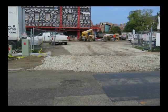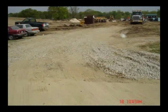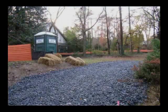Rock construction exits provide an area that allows soil from vehicles and equipment to fall off tires prior to being tracked onto the primary road. Thus, to be effective, egress from the site must be limited to the exit road. Exit roads need to be maintained periodically. This can be done by adding new layers of stone as the old layers become compacted.